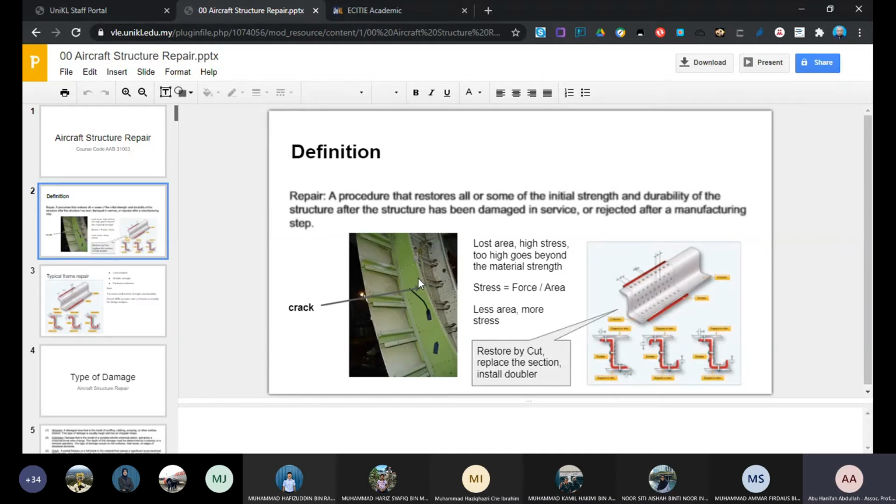You can see here the bulkhead, the frame here is heavily constructed. We have an angle cap here, an angle cap at the bottom here, and everything is attached to the fuselage skin. So this is heavily constructed because it carries a lot of load. They carry shear load. They also reduce the column length of the fuselage. So this area is heavily loaded. The structure basically carries the load circumferentially. For the stringers, they carry a load longitudinally along the aircraft fuselage horizontal axis.